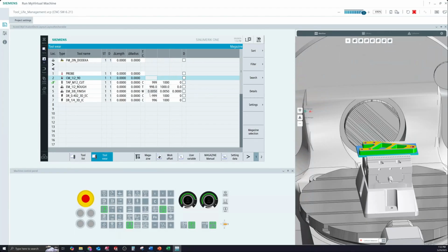So at that point, we need to tell your operator that as this starts getting some time on it, or whenever they change a tool, they need to come in here and reinitialize or reactivate the tool. So even though this doesn't reach 0, because remember, we don't ever want this to reach 0, when they change the tool out they need to hit reactivate. When they hit reactivate, it will reset this tool life back to whatever the set value is. They can either hit reactivate or they can just type it in. Either way, doesn't really matter. But they do need to hit reactivate.